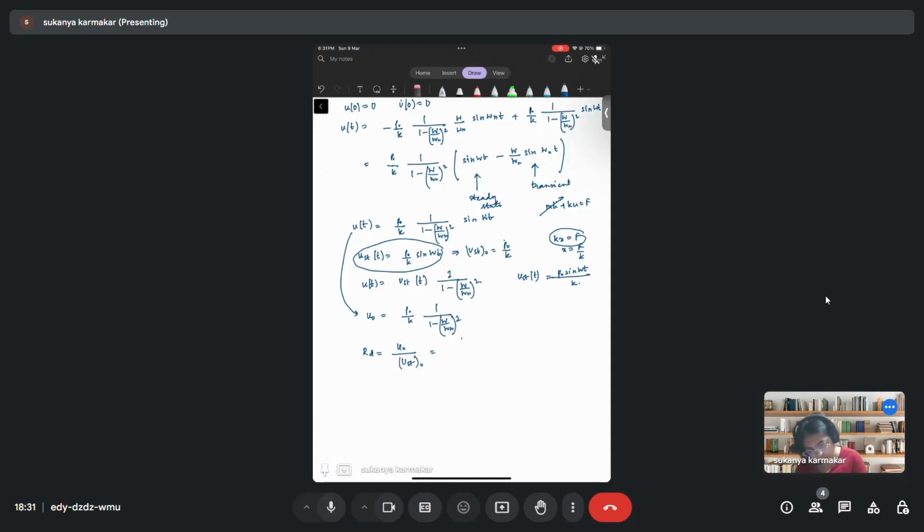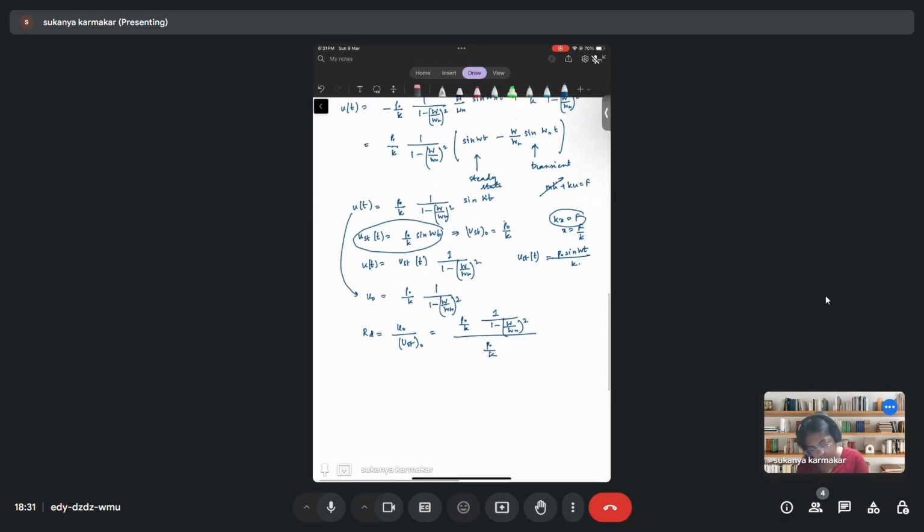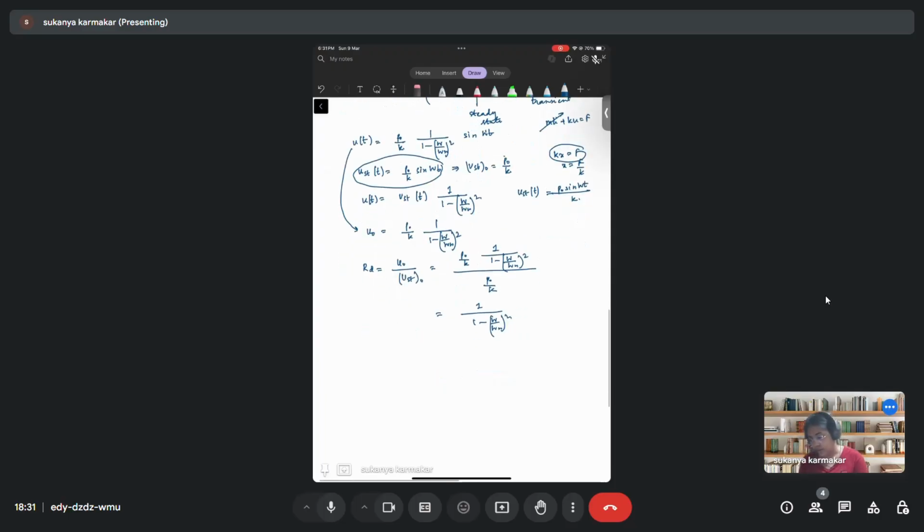So what is u naught? u naught is p naught by k times 1 by 1 minus omega by omega n whole square, and ust naught is p naught by k. So Rd is 1 by 1 minus omega by omega n whole square. So how did I get it?